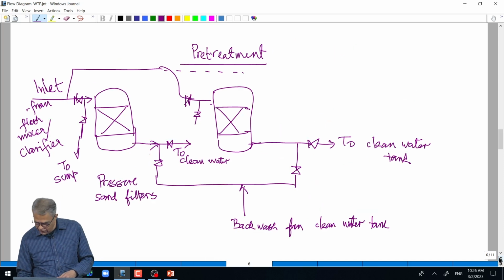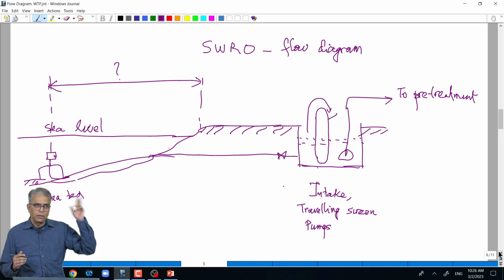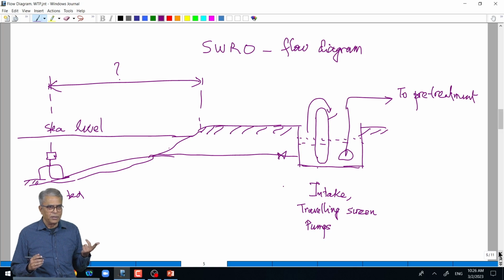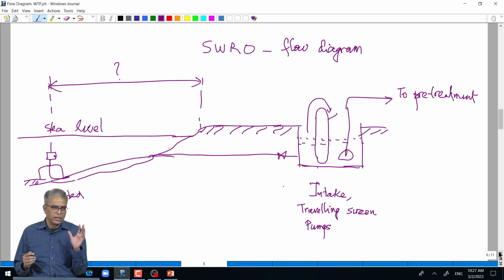Now, switch to RO, where I said if it is 1 crore, it is 9 crore per MLD. So, it is very expensive, 9 times expensive. Now, we have to trigger: show me the flow diagram, why the hell is it 9 times costlier, I mean 8 times, why is it not 20% more expensive? That kind of analysis we are going to do. Similarly, 11 rupees per 1000 liters, there I said 85 rupees per 1000 liters. Come on, pull out the flow diagram again and ask why it is 85 rupees; that analysis is key.